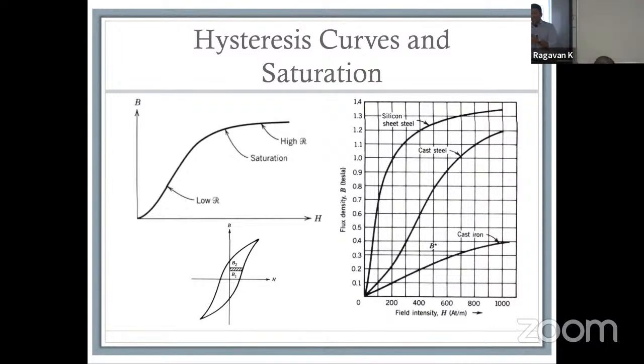In order to eliminate that entire flux, you have to apply a negative current. So you actually have to apply a negative current. Keep in mind, H is a function of N dot I. So it's a function of ampere turns. The more current you have, the more, so you're going to apply a negative current to extract this energy.